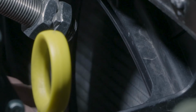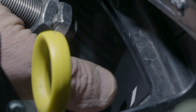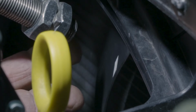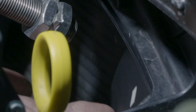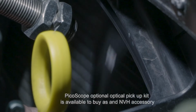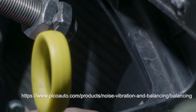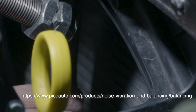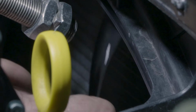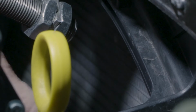How can we determine the speed frequency of this fan? Remember, speed and frequency, one and the same. We attach some silver tape here and point the optical pickup at the cooling fan. So every time the optical tape passes the optical pickup, it generates one pulse per revolution. That will give us the frequency of the fan. We can then use PicoScope to not only count those pulses but display the frequency of those pulses, which should come out around about 36 hertz, because that's where we captured our peak amplitude vibration, at 36 hertz in NVH.